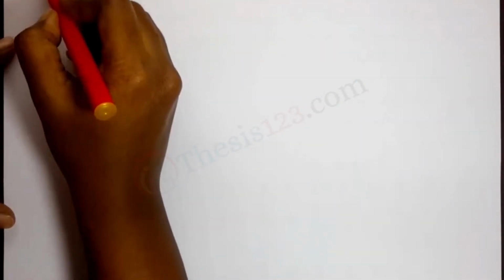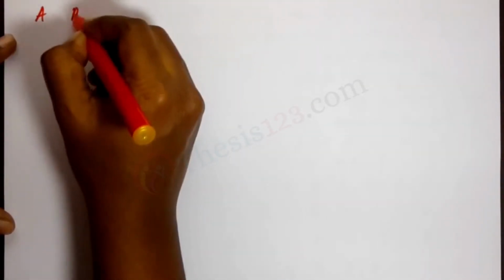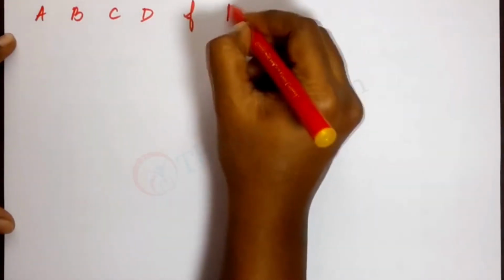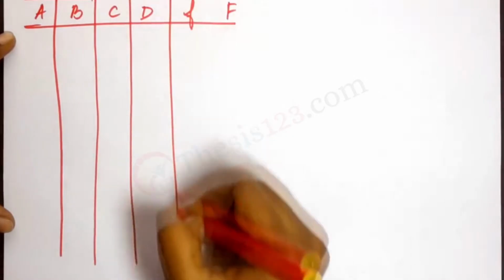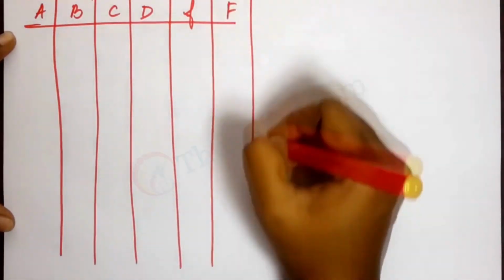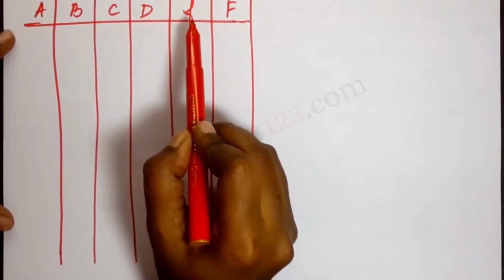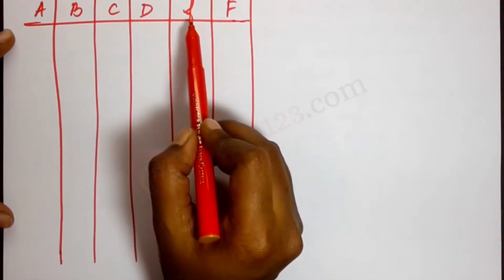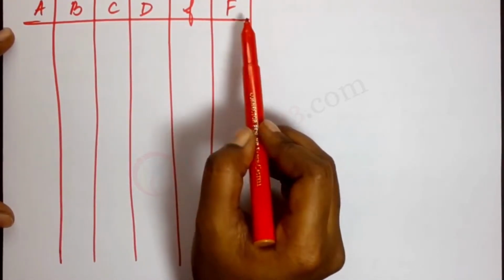Now the next step is to note down the truth table. The truth table is drawn from the K-map that we just worked out. Okay? So we have our columns A, B, C, D, f and F. Now, small letter f here denotes the value of the min-term expression that we drew in the K-map, and capital F denotes the input to the multiplexer.